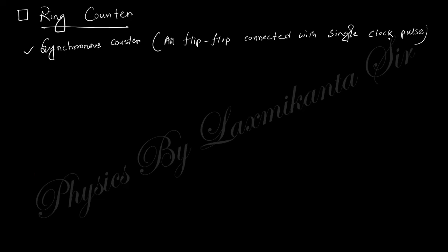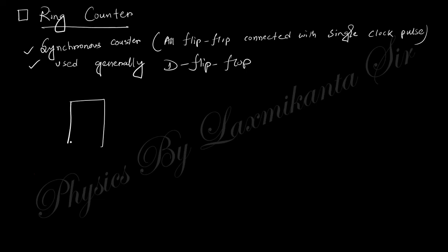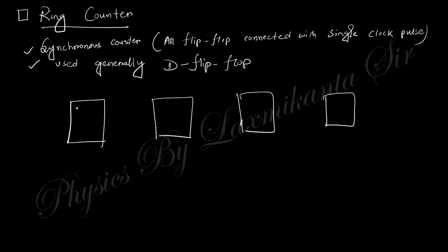That means here we generally use D flip-flops. Suppose this is flip-flop 1, 2, 3, 4. This is D3 corresponding to Q3, D2, Q2, D1, Q1, D0, Q0.